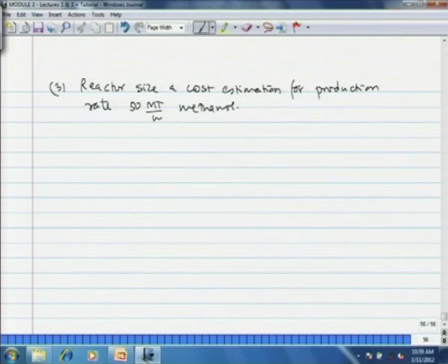However, all of the CO is not converted, so we have to take into account the equilibrium conversion, or let us say the 95% equilibrium conversion. Maybe we can assume a little bit less, let us say 90%, to make sure that our reactor operates. Okay, so we note here design conversion, we shift from 95% to 90% just to make sure that our reactor operates. Okay, 95% is very close to equilibrium.